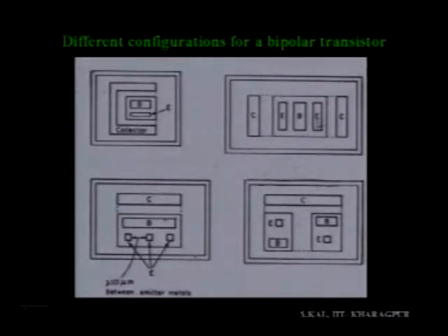Okay, so two emitter contacts, or sometimes we use one emitter, two base, or two emitter, three base, like that, when we go for high frequency transistors. Sometimes this sort of structure is very useful in order to increase the fT values. For high frequency transistors, the main emphasis should be to reduce the parasitic capacitance and other parasitic components, so that the frequency fT, or frequency of operation, will be high. This sort of structure can reduce many of the parasitic components like capacitance and resistance.